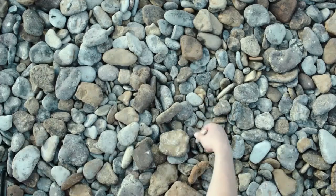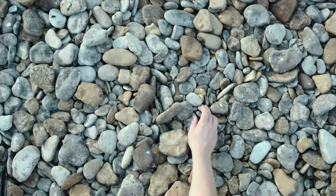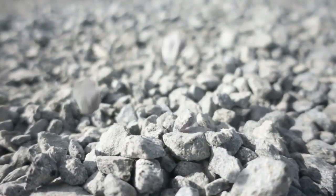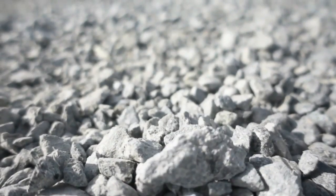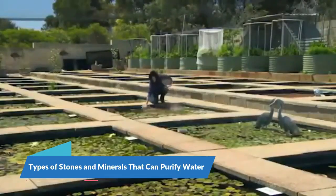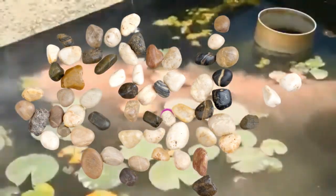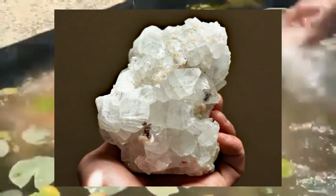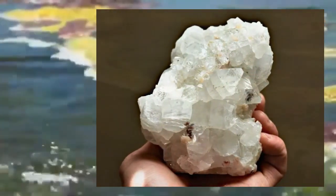This section will discuss the types of stones and minerals used in water purification, detail their specific purification mechanisms, and provide examples of their application in real-world scenarios. Types of stones and minerals that can purify water. Number 1. Zeolites. Zeolites are microporous, aluminosilicate minerals known for their ability to undergo ion exchange. They are highly effective in removing contaminants like heavy metals, ammonia, and other nitrogenous compounds from water.